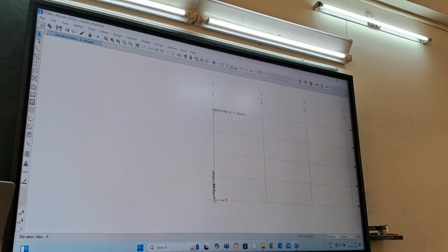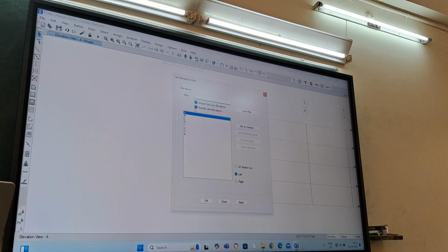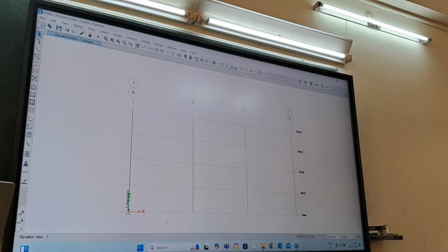And one more thing is, at this point we are actually analyzing in the x direction. So this is our x. The direction where you are applying your load should be provided with some restriction, meaning movement should be restricted in this direction, then only it will be able to calculate the reactions.